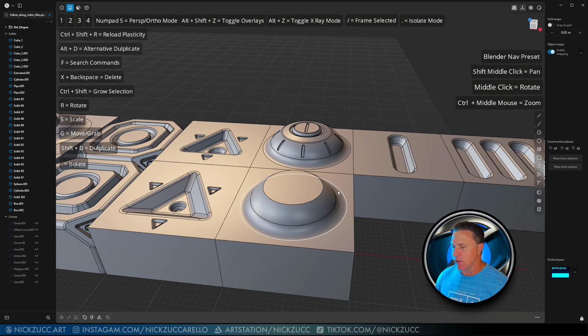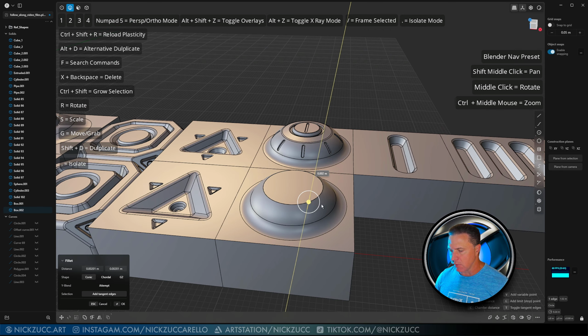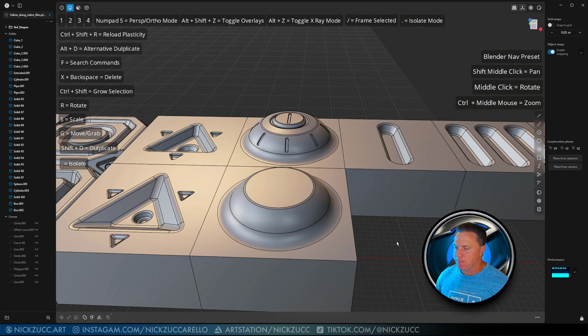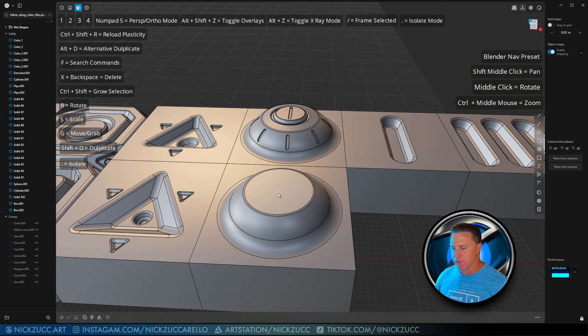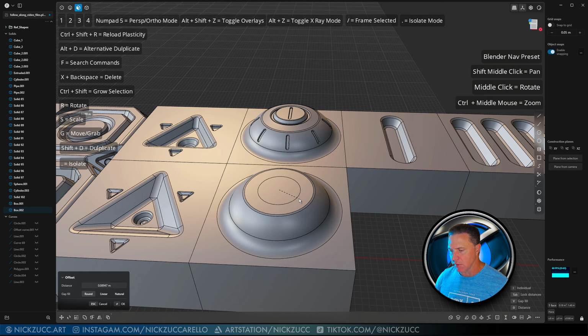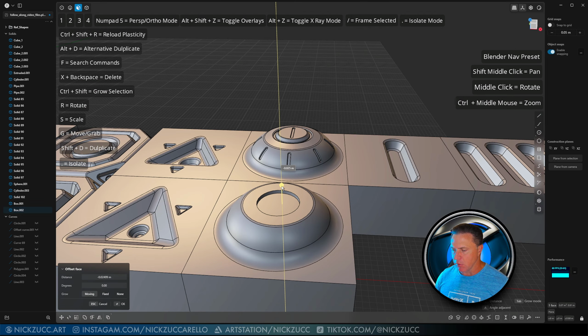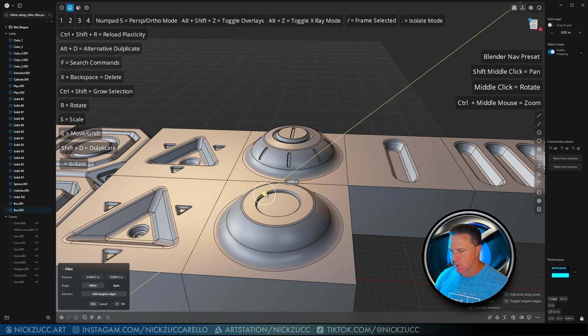I'll just select the curve, tap H to hide it, and again we'll tap 2, and we can either fillet this and make it nice and soft, or we can go this direction and do a chamfer. So it's up to you what you want to do with that. Okay, so that should be nice and flat for me. At that point, if I want to take this face, tap 3, I'll do O, and I'll offset that just like this a little bit, just in here. I'll grab this, pull this down like this, tap 2, do a chamfer right there like that.